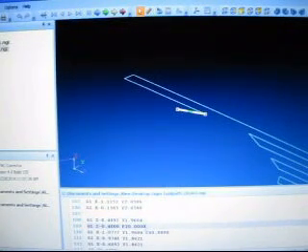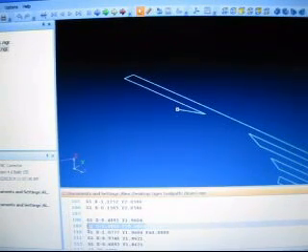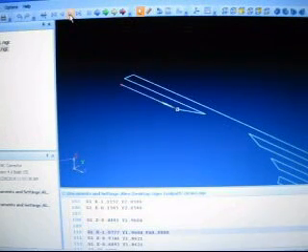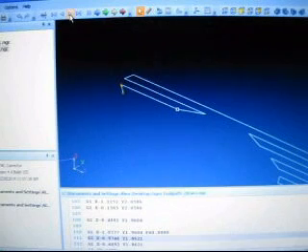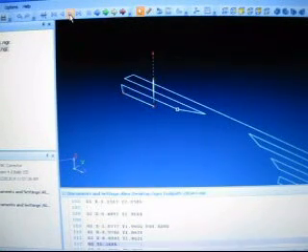Okay, now our next line of code is this line of code right here. This is what used to be our plunge to that position. We don't need it. We're just going to cut it. Okay? We're cutting that. Delete. And then our next line of code continues on its merry way, which is what we want. And it's just going to come back here and do its thing.